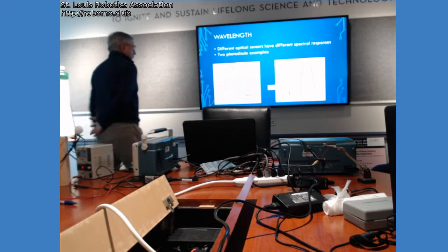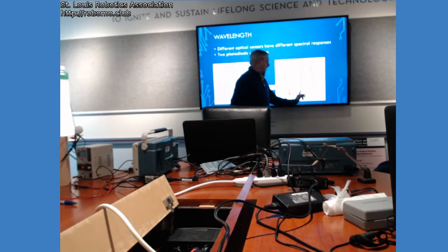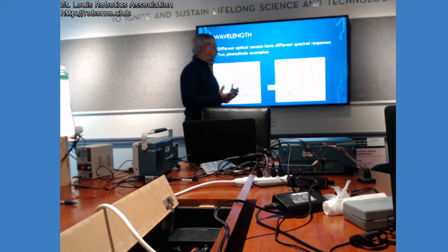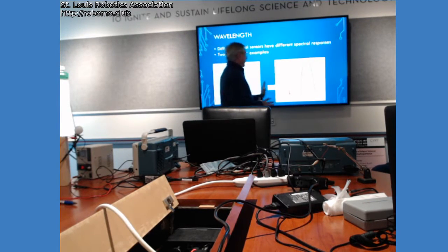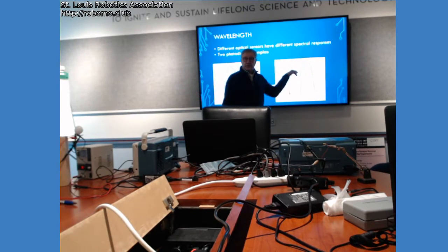Yes. So we're going to talk about saturation in a little while. If you wanted to make something work out here at say 900 nanometers, which is near infrared, and have it be completely blind to all the room lights and everything, this is the detector to choose. This is going to knock all that out.